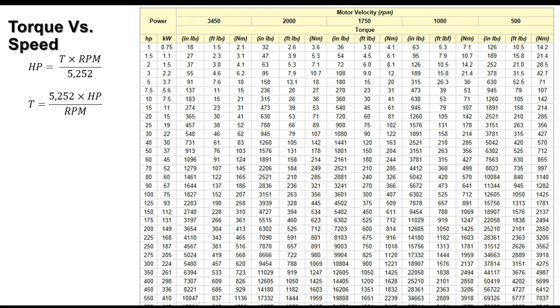Because why? Because the motor's running at a slower speed, right? You understand? So saying a 1 horsepower motor would generate the same torque as another 1 horsepower motor, all depends on the speed that 1 horsepower motor runs at, right? You understand? So a 1750 RPM, 1 horsepower motor would generate more torque than a 3450 RPM, 1 horsepower motor. So that's the problem with horsepower and torque, is that torque is that twisting motion that causes things to move, and it varies with what? Varies with speed. Torque varies with what? Speed.